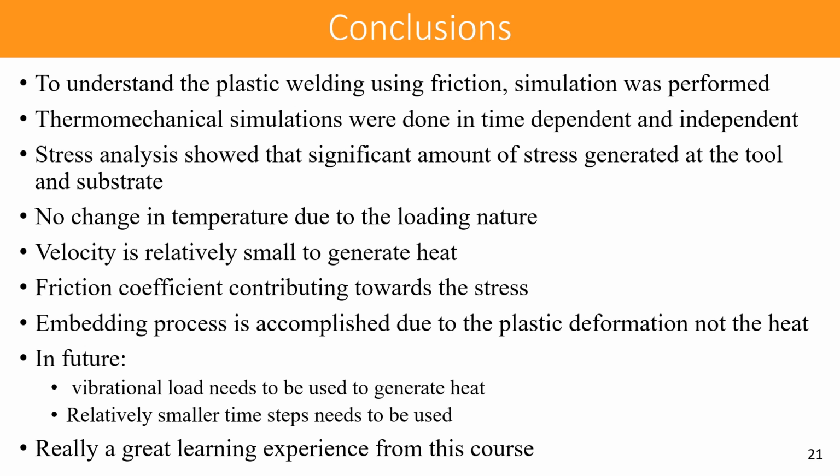And then the stress analysis showed a significant amount of stress generated at the tool and substrate, but there is no temperature change due to the loading nature. Since the velocity is relatively small, it's not really generating heat at the interface of the substrate and the tip.